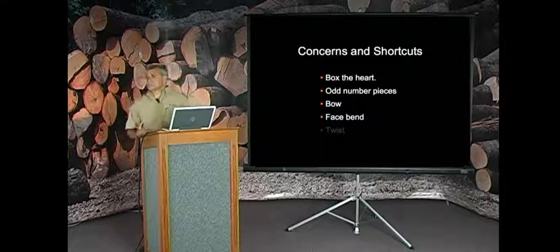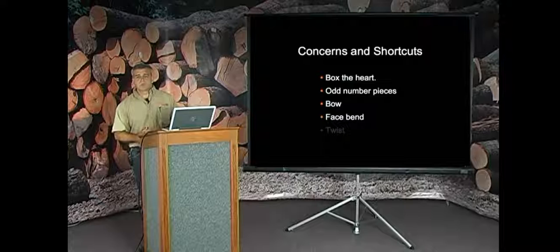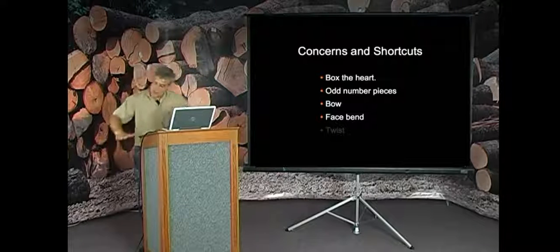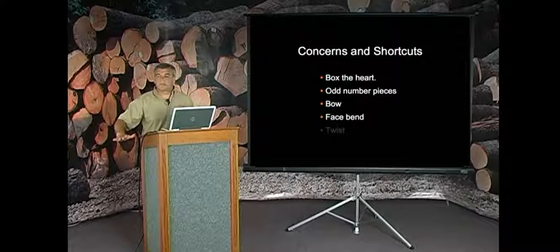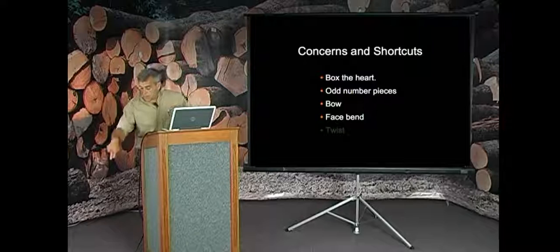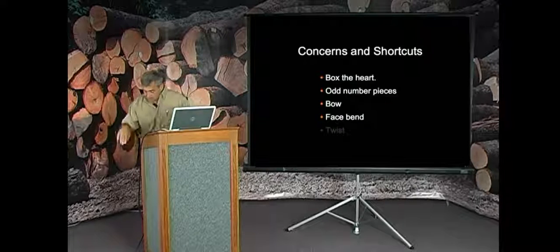What about face bend? You're cutting a piece of wood and you see that the ends are trying to lift and the middle's staying down. Can we use face bend somewhere better than we can use it somewhere else? Well, I think so. Face bend for sheeting. If you nail one end of the board down and you nail the middle and on down to the other end, you can get it to lay flat. It'll lay flat for you.